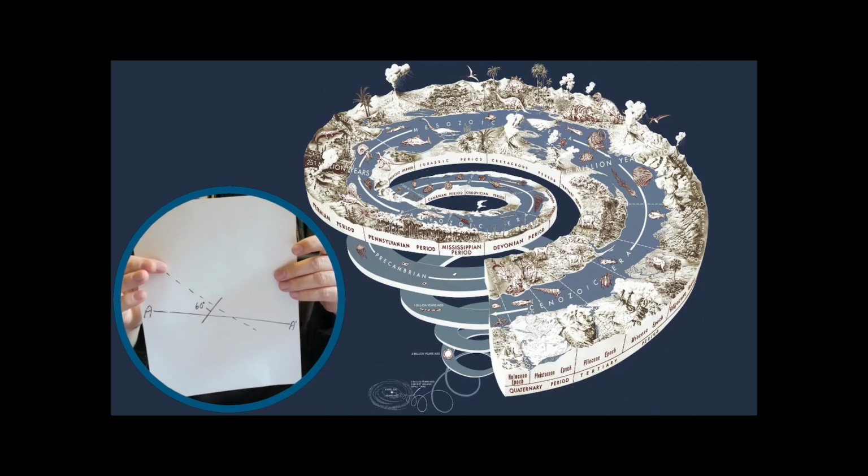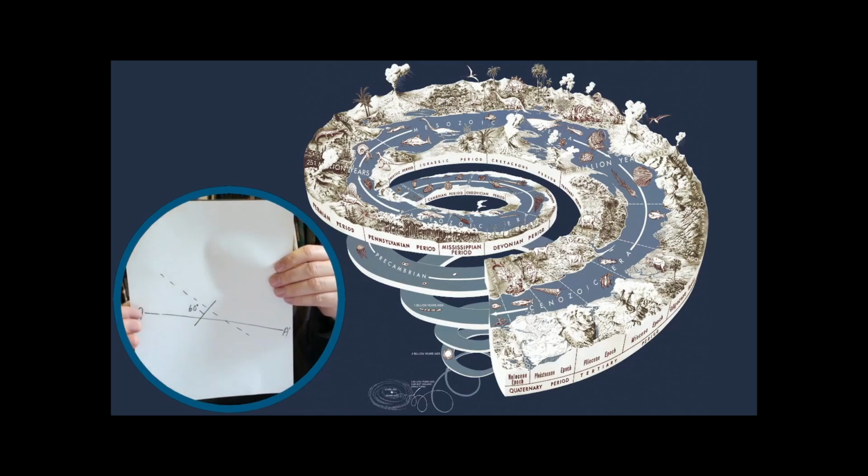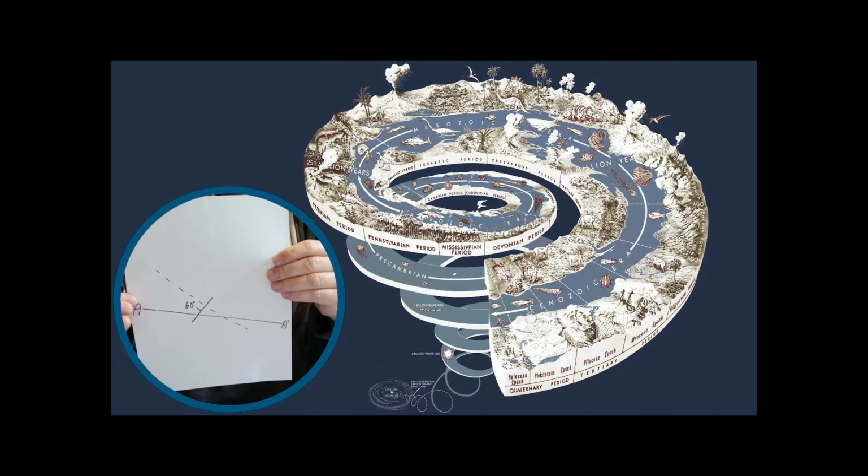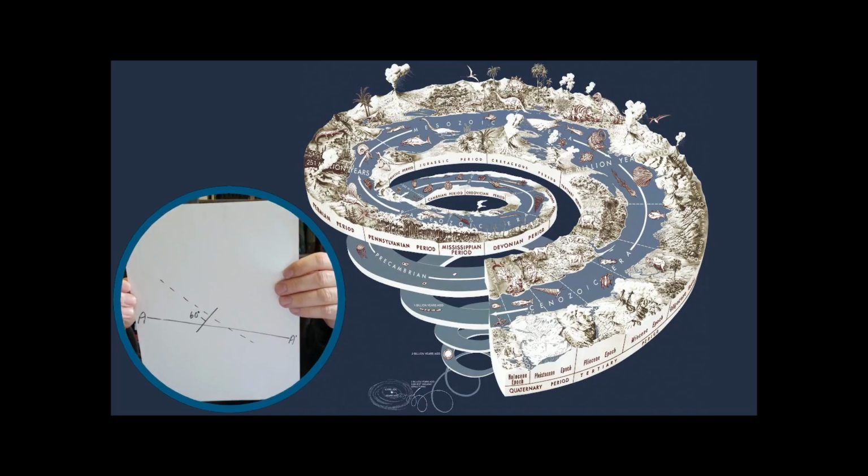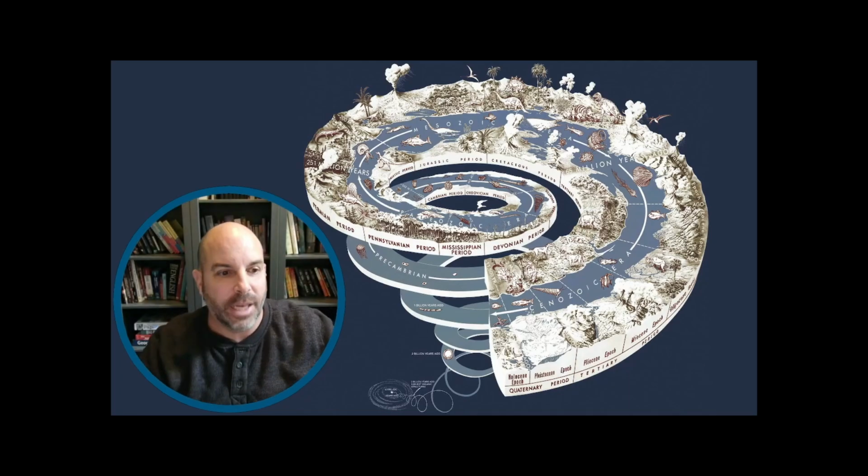But for example, if we had to draw our cross section along the A prime line, notice that we are now not perpendicular to that. But we know the orientation of this line, which is roughly 285 degrees, because we can measure that directly off of our map. So let's imagine this scenario, and what we want to do is calculate what the apparent dip of this 60 degrees is so that we can accurately plot that on our cross section.